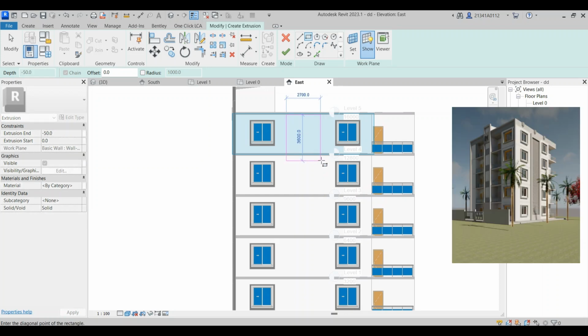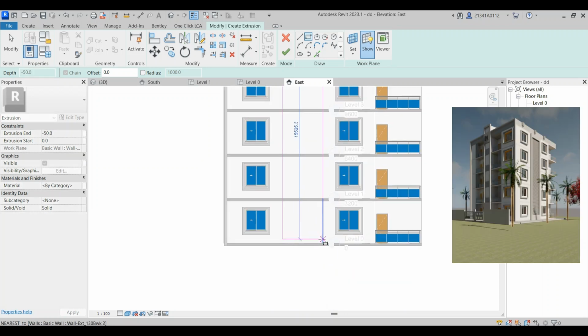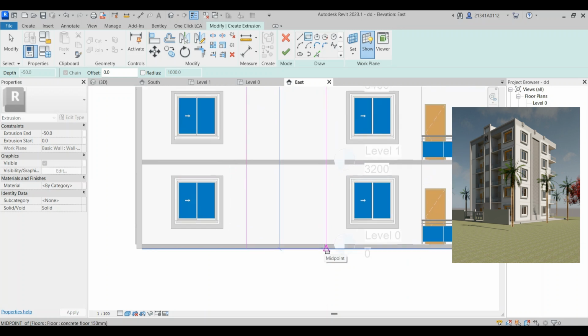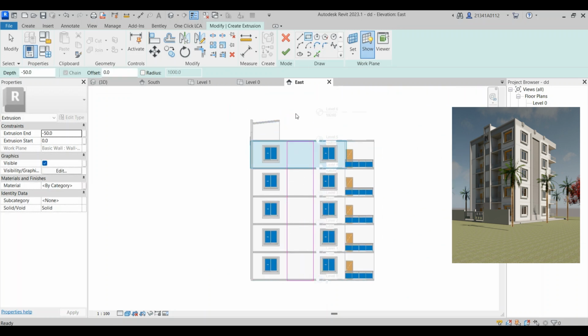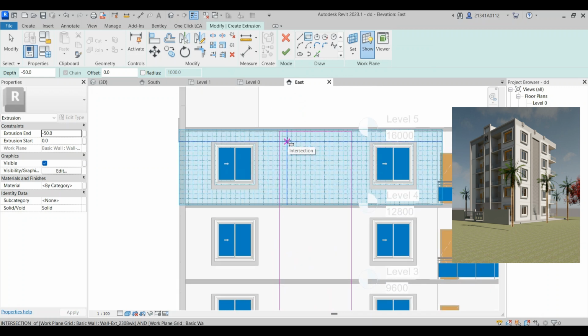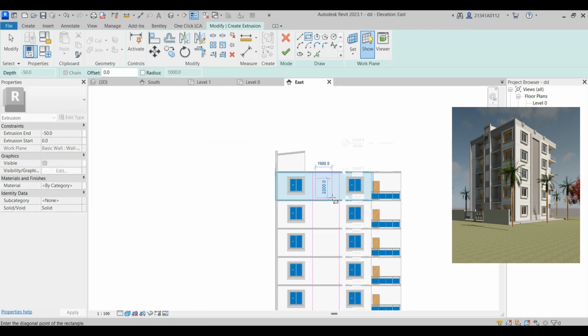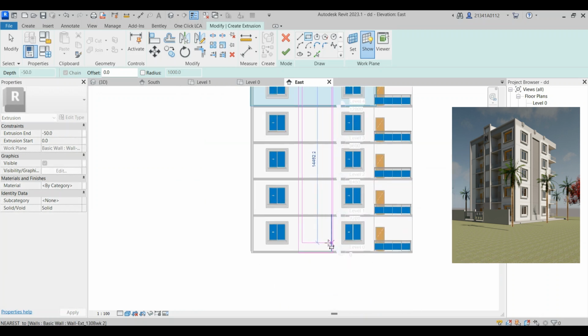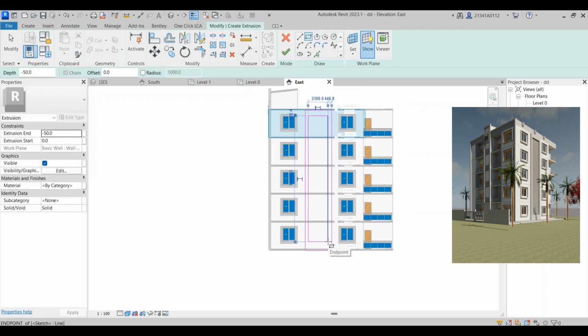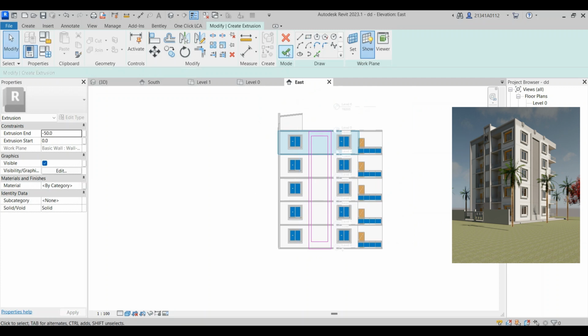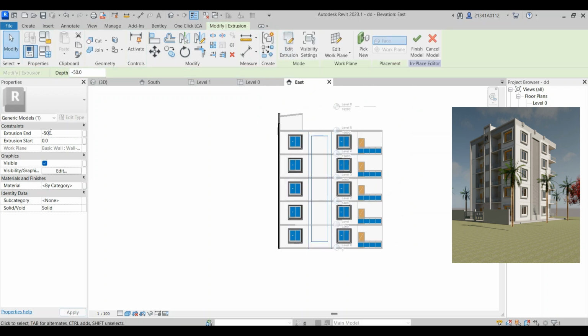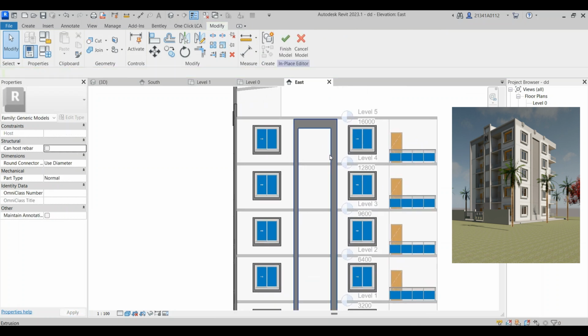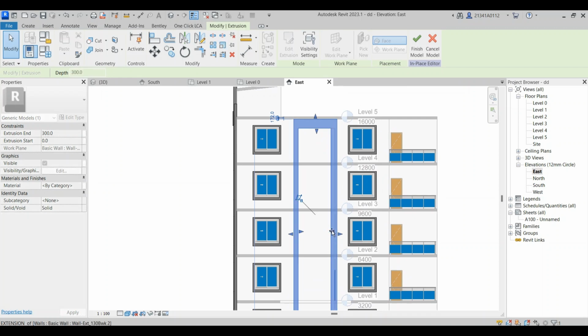Now I can make another extrusion. Can you observe this in this reference image? First I do the framework of this extrusion. Take the rectangular line tool to draw the framework of this extrusion. After that, change the size of the extrusion and also adjust the shape.